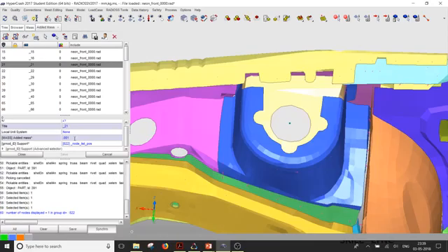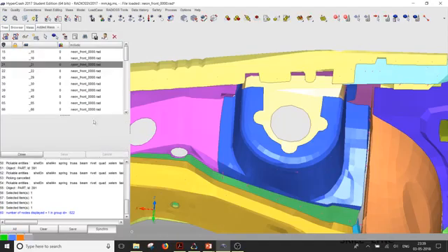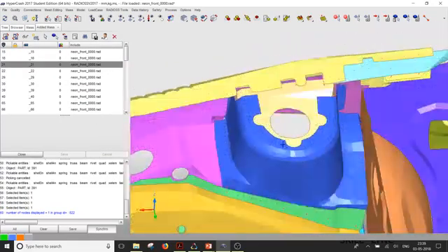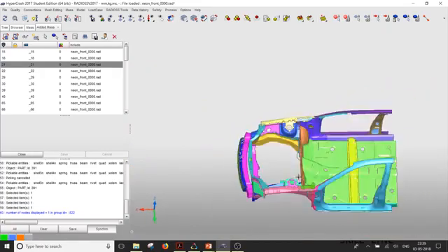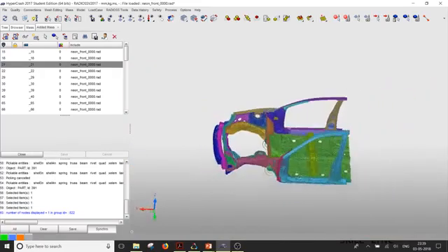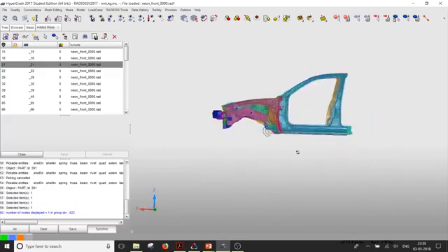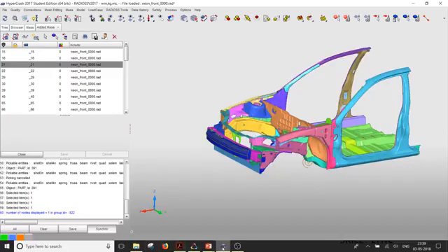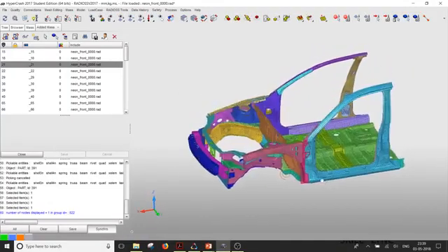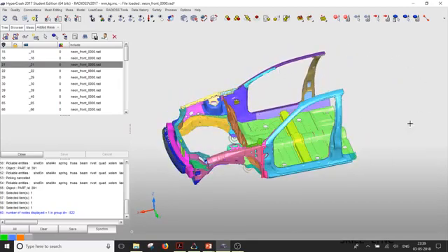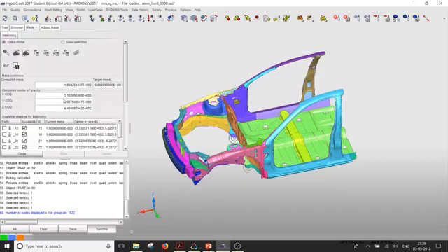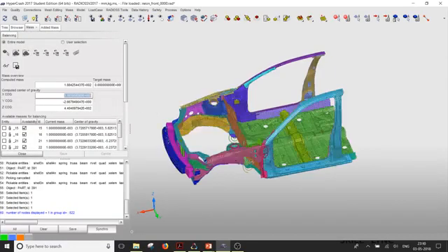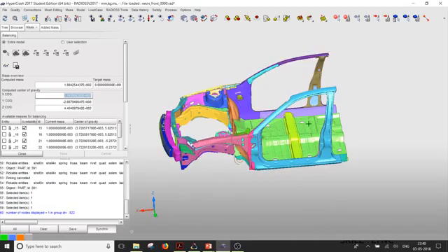Now I'm not sure if I really care about that mass with 1 gram. So in that case, I can maybe delete those masses and then look at the system as a whole and decide where I want to add the masses. Ultimately, what you need to do is open the 300k model, that is the higher resolution model with all the parts included, and do the balancing. You'll have to see where the CG is coming up. You have to match the CG with that particular number.